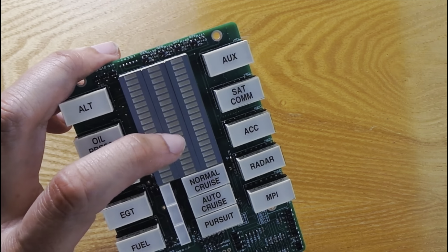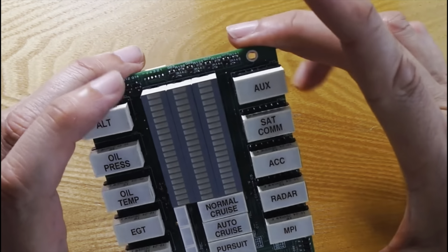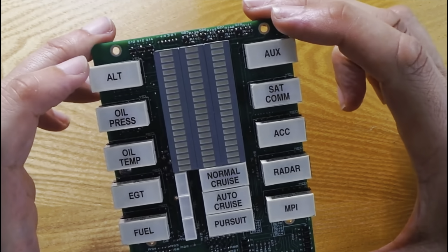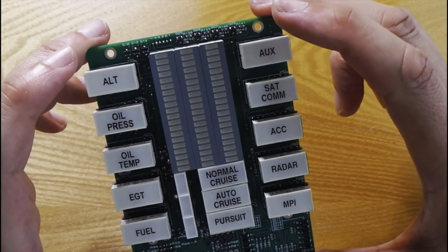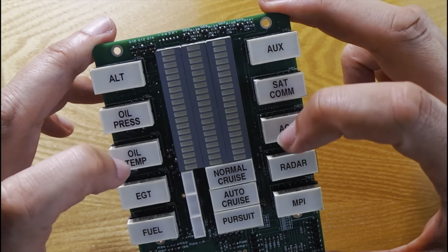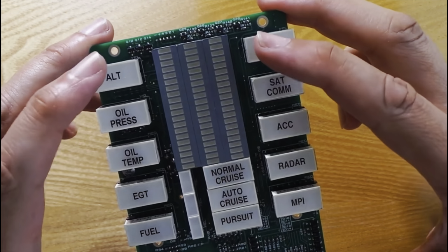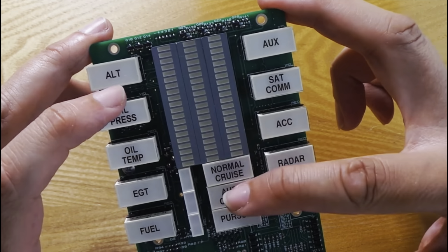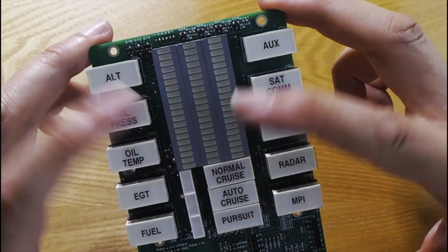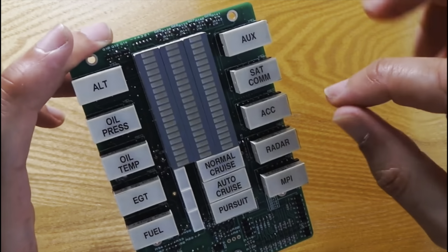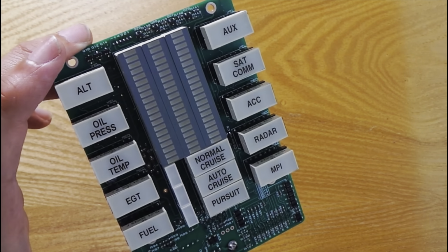A short press of push button number 1 will actually cycle through those different functions that we mentioned for the indicators. So it will cycle around the sequence of nothing functional and all on, or nothing functional but things are in show mode, or normal auto pursuit only are functional and the others are all on, or normal auto and pursuit indicators are functional and the other indicators are in show mode, or everything's functional. And then it will go back around again. So single short presses of push button number 1 will cycle through those options.